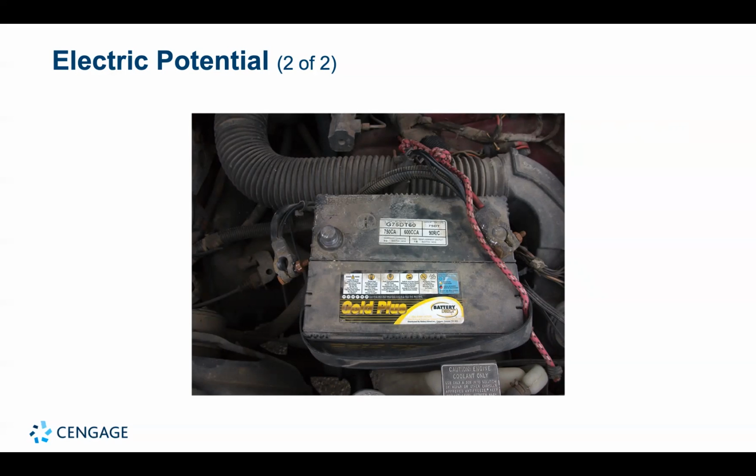The battery provides the electrical current necessary to operate headlights, a radio, power windows, and motors. Think about a charge of 1 coulomb to be moved around a circuit with a battery and a couple of these external devices. As the charge is moved inside the battery from the negative terminal, which is at 0 volt, to the positive terminal, which is at 12 volts, the work done on the charge by the battery is 12 joules. Each coulomb of positive charge that leaves the positive terminal of the battery carries an energy of 12 joules. As a charge moves through the external circuit towards the negative terminal, it gives up 12 joules of electrical energy to the external device. When the charge reaches the negative terminal, its electrical energy is 0 again. At this point, the battery takes over and restores 12 joules of energy to the charge as it moves from the negative to the positive terminal, which allows the charge to make another transit of the circuit.